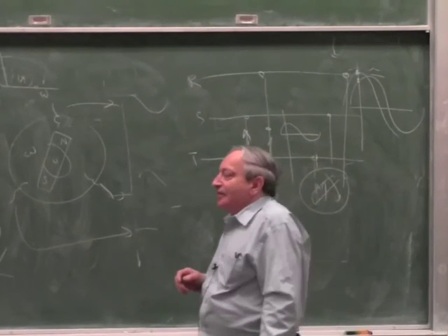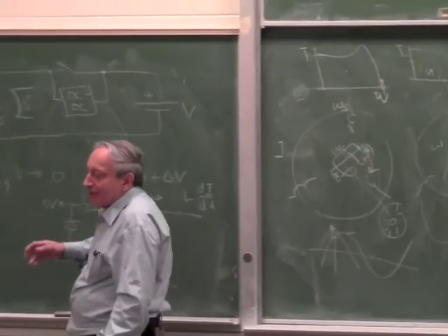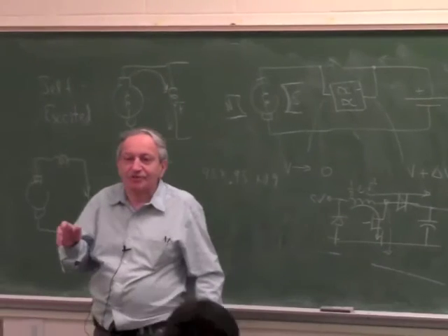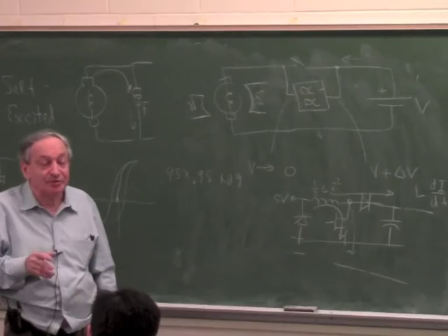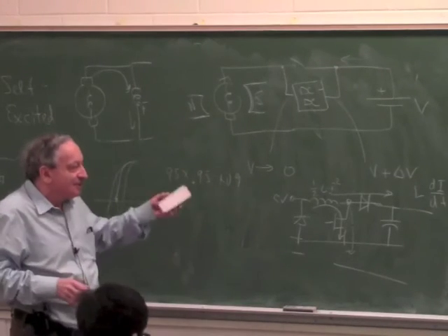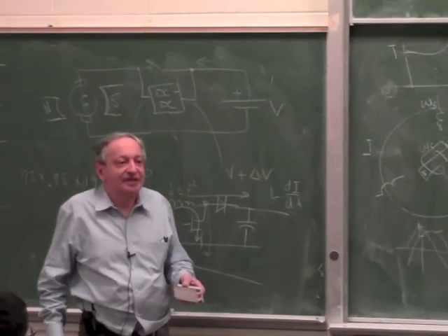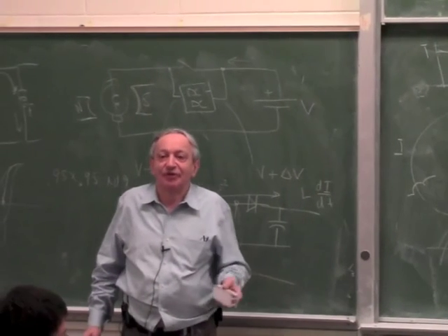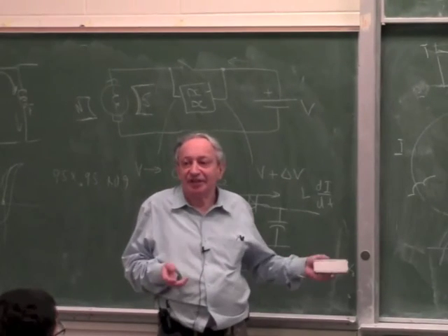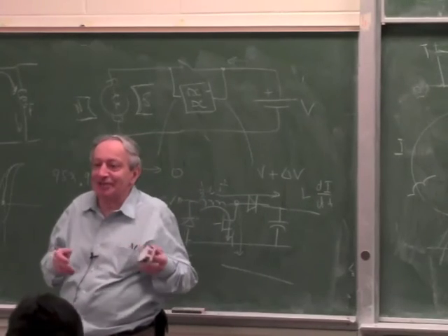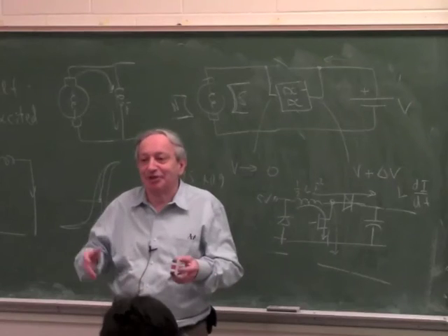Okay, good. Now, all this theory, which we always talked about, electromechanical actuators, sensors, motors, also applies to hydraulic and to pneumatic, because the basic concepts are the same. If you have, let's say, a hydraulic servo, and you have a pressure accumulator, the pressure accumulator behaves like an inductor. It stores up energy and has all the same problems. If you want to shut off the flow right away, it doesn't let you. The pressure goes up suddenly.